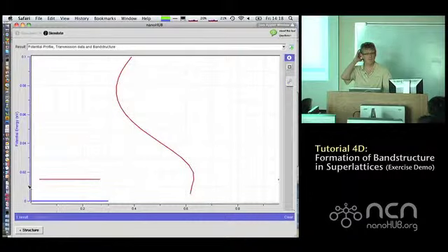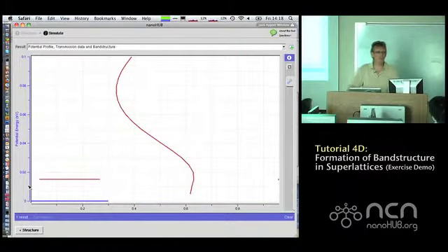That's 1 kT. So the point is, if somebody shows you a quantum transport simulator that says, I don't vary my effective masses, all I vary is my barrier height, you should laugh him out the door. Because a different material has a different effective mass, and you can't neglect the effective mass variation.